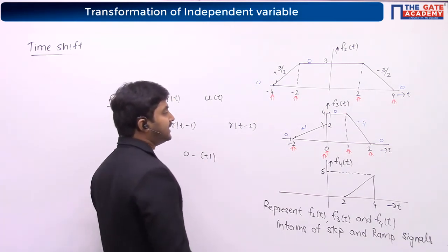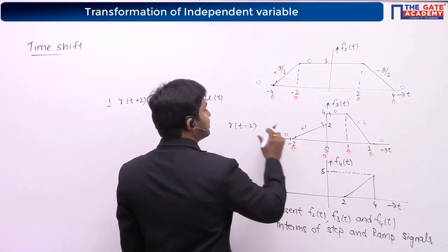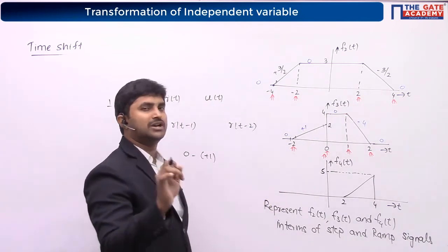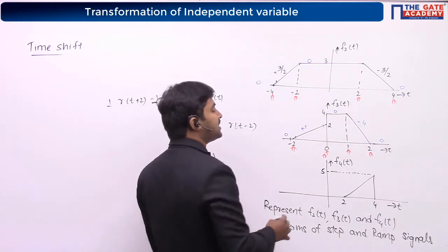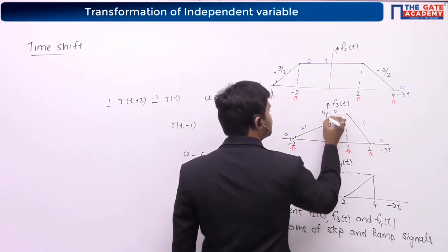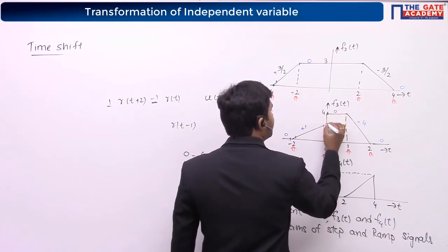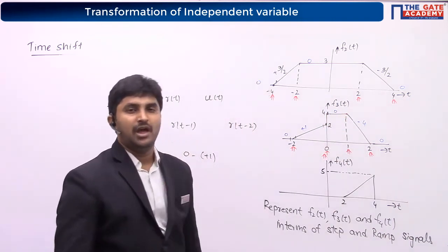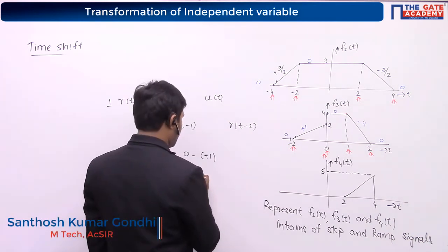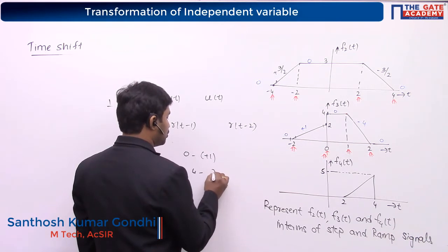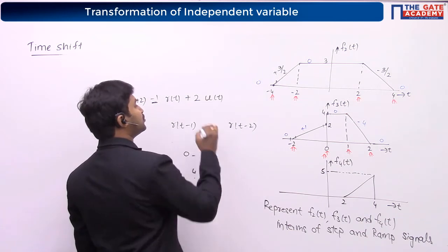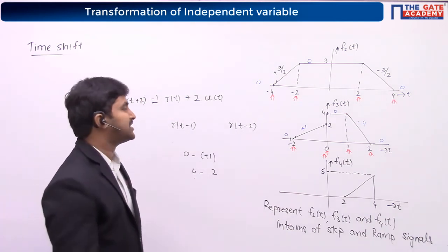Okay, and there is a step as well. So whenever we are talking about a step, we will not look at the slopes, we will only look at the amplitudes. So you can see, after crossing t is equal to 0, the amplitude is 4, before crossing it is 2. So 4 is the final amplitude, 2 is the initial amplitude. 4 minus 2, it is +2.